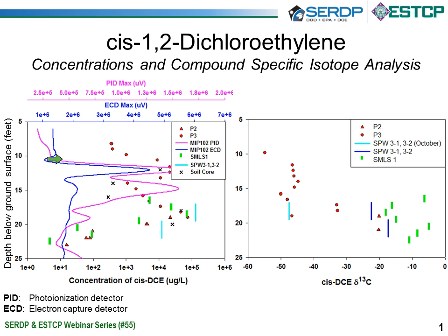Finally, we have the results of the direct push technology, the PID result, and the ECD result. The direct push technology did a good job in identifying the first chlorinated solvent peak, but it did not do such a great job on the second chlorinated solvent peak. There was really no response from the ECD here, even with 100 milligram per liter concentrations of chlorinated solvents.